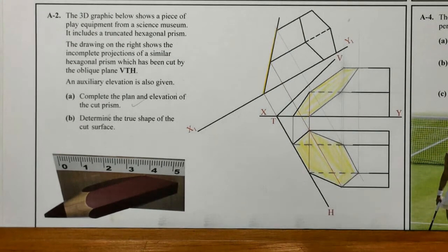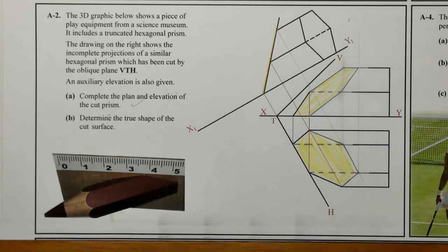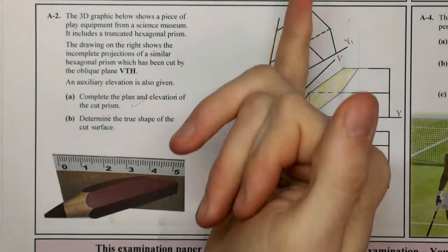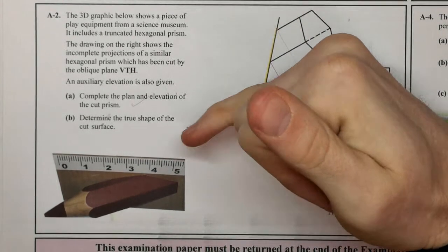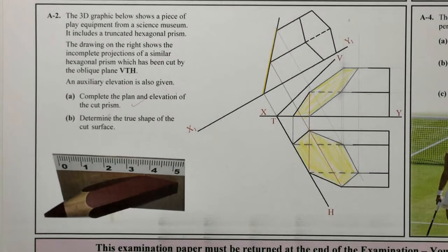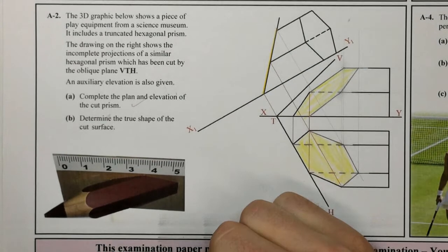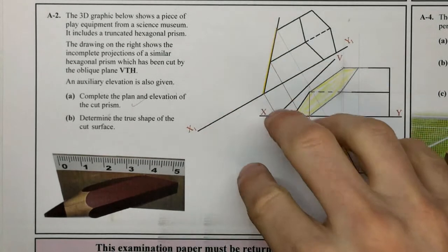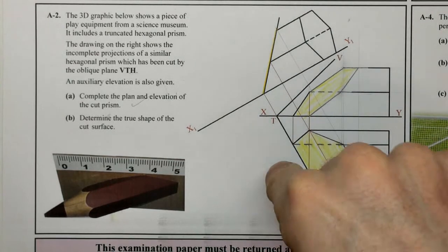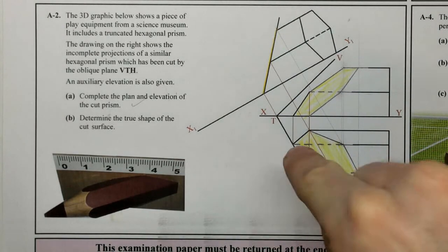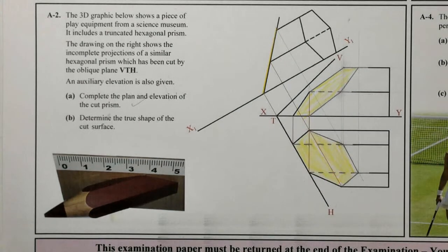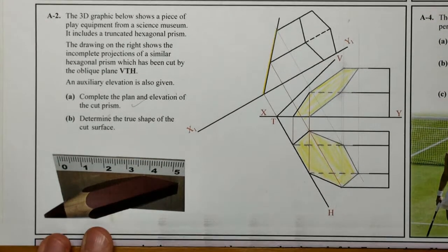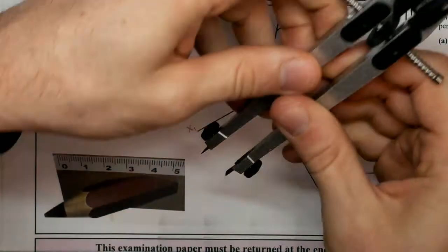But just looking at the marking scheme, I can see that they have done a rebatment, okay, which is just fine as well. So what we're going to do is we are going to take that edge that we have, and we're going to rotate it so that it's resting on the horizontal plane. Okay, once it's resting on the horizontal plane, then we can find it in plan, because when we look down on top of our plan, if it's resting on the horizontal plane, then we're looking perpendicular to it. Okay, so let's take that rebatment.